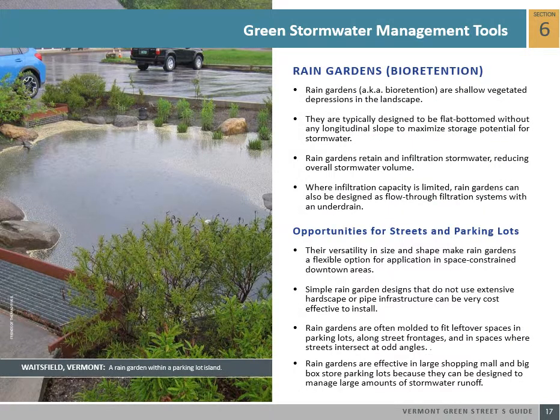Rain gardens have many active transportation, urban ecology, and neighborhood enhancement benefits. They can allow for separation between sidewalks and vehicular traffic lanes, creating a safer and more walkable environment. They can provide additional stormwater storage and flow reduction, as well as pollutant filtration, which helps prevent damage to downstream water bodies. They can significantly help with placemaking and provide community public space. Rain gardens typically cost between $8 and $50 per square foot, depending on retrofit conditions or new construction, and if the rain garden has landscape side slopes or vertical planter walls.